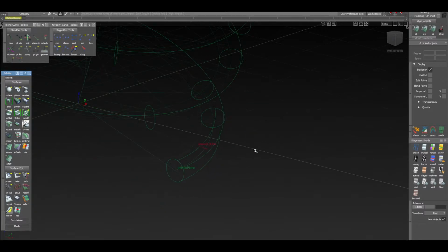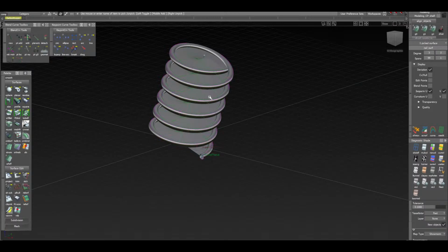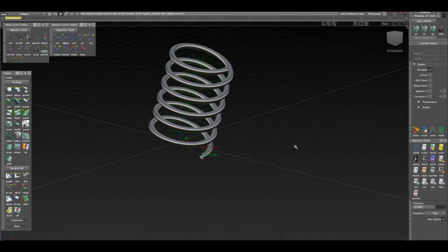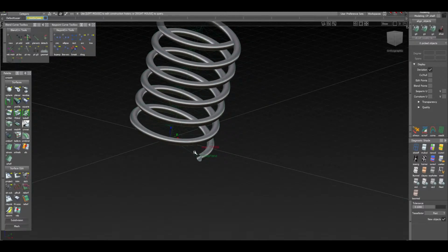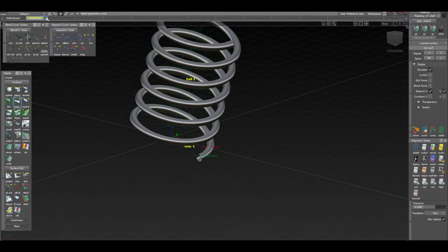And once you create your curve or your tube, obviously you don't need the surface anymore. You can delete it. Actually, what I'm going to do is create a new layer. I'm going to call it "just in case," in case I need the data for later on. I'm going to query edit, pick the object, and assign it to the just in case layer. Turn that off, close this window.